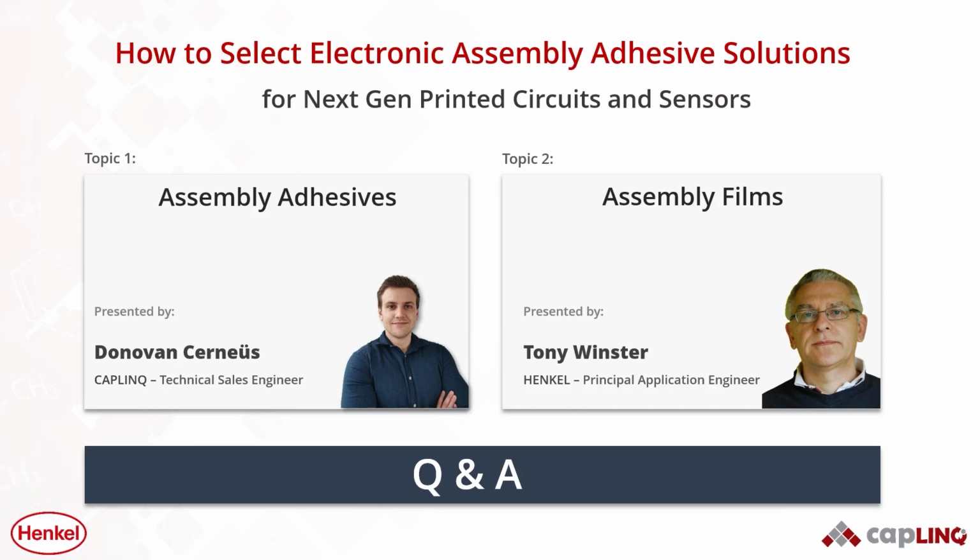But to specifically answer the question, those wafer level films tend to be a lot thinner. They're typically 20 micron thickness, so they're relatively easy to dice through, whereas the assembly films we've been talking about are thicker than that, typically 100 micron. So dicing is more of an issue. I wouldn't say it's impossible, but it's a slow old process to dice through these.